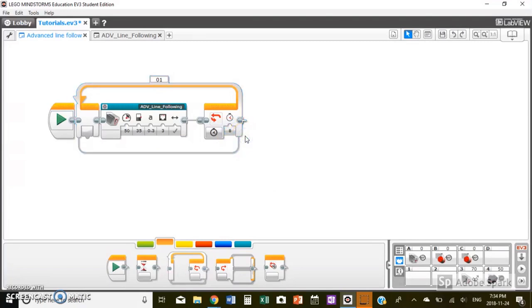And before I show you the program recording of it, I want you to see the light value, and as I've set it to 35, watch as it makes its corrections. Oh, and I would recommend keeping the KP value at 0.31. That seems to work best for my robot. And I'll keep the speed at 0 just to show you, since the lines on my paper aren't exactly printed. It's kind of sharpied. Anyway, download and run. Let's see what happens.